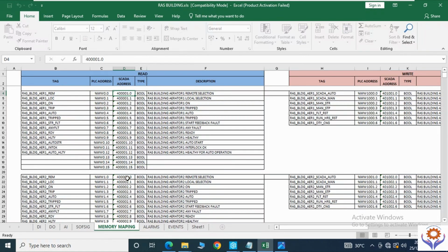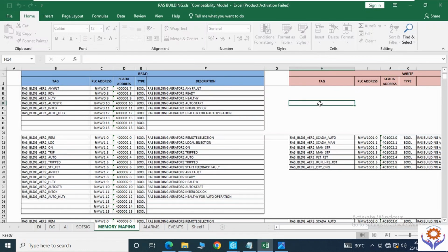Okay, because in the PLC and SCADA, whatever address you have in the PLC, for example memory word MW30, in the SCADA you have to put 40031, because this is based on the SCADA systems. Maybe some SCADA systems have the adjustment in the SCADA itself, +1. Whenever you add it, it will automatically be +1 in the script. But the usual practice is, whatever address you have in your PLC, it should be added +1. Okay, this is for Boolean.